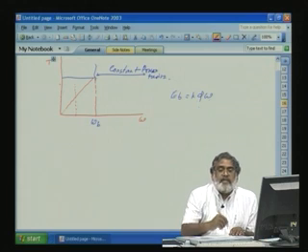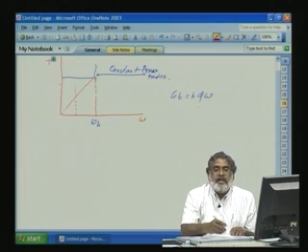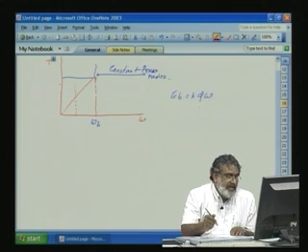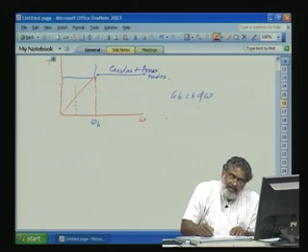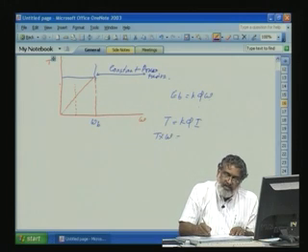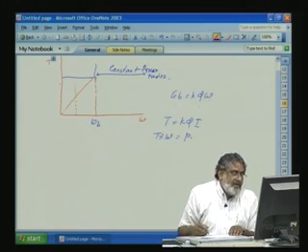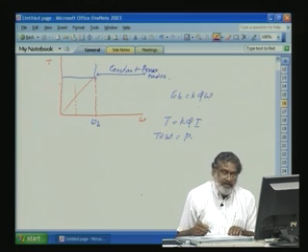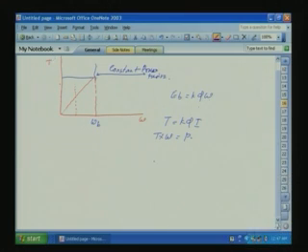See, we have reached the maximum voltage and current. We cannot go beyond this one. So this power is limited, but the speed we can change by changing the flux. Now, how will it be? Let us say T, we know it is K phi into I armature current, and we know T into omega is equal to P, power. For a separately excited machine, what is back EMF? K phi omega is equal to V minus I armature R.